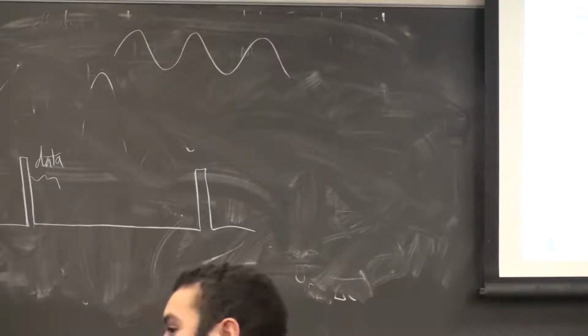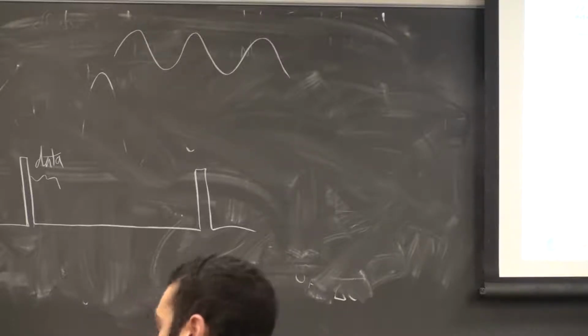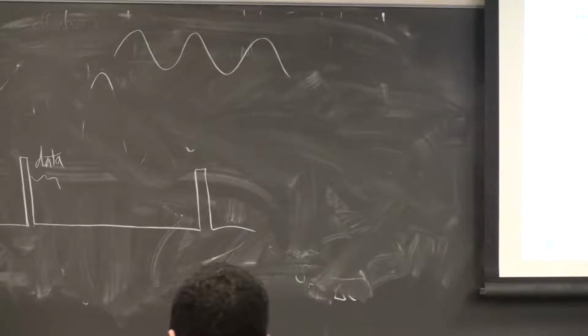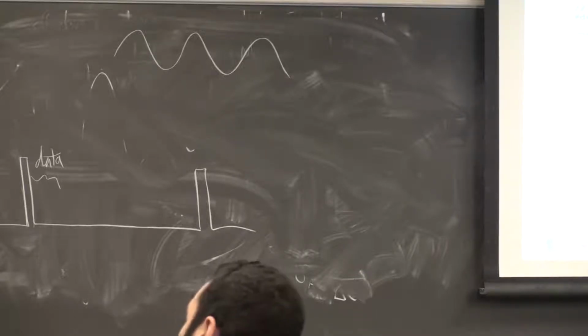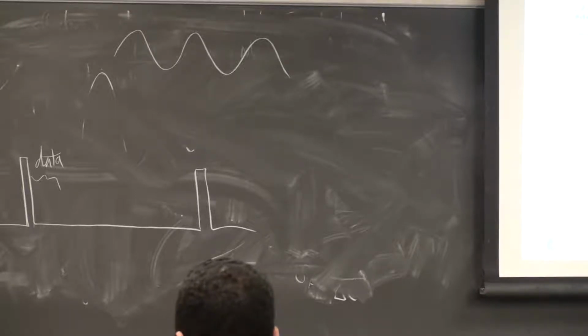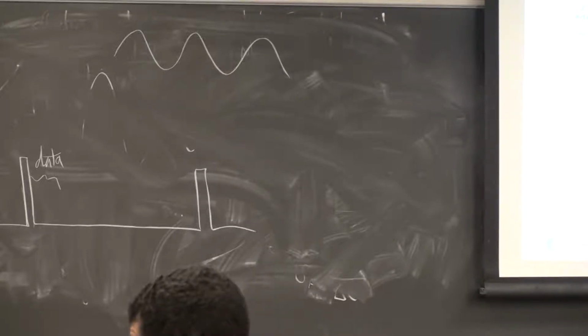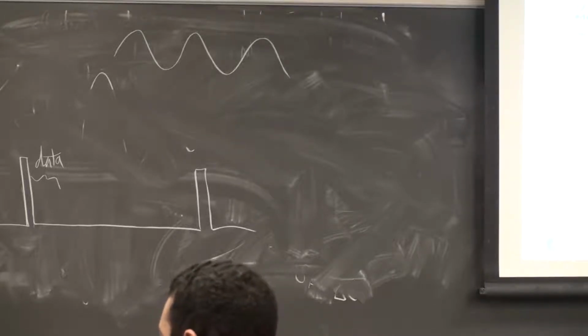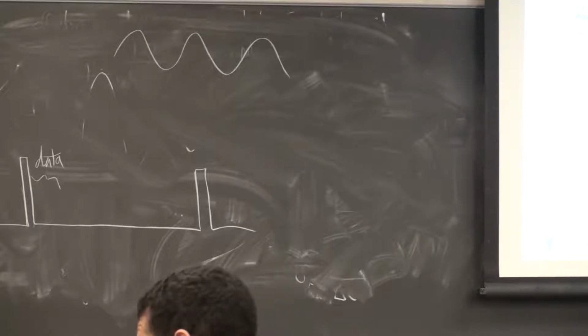There is a shadow flag. There's an interrupt flag which is noticed by the interrupt controller, and there seems to be a separate flag, if I read the hardware description correctly, that is noticed by the DMA controller. You can't clear that. There is no call to do that. But DMA is doing it by itself.